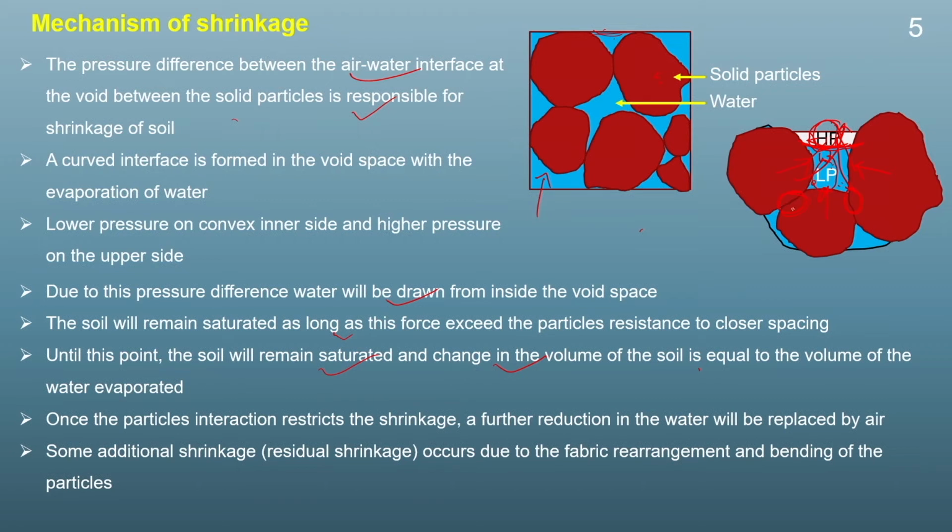But once this resistance force exceeds the pressure difference, then there will be no further movement of the solid particles, and there will be no change in the volume of this soil sample. But with a further decrease in the water content or amount of water, the air will start to enter. So, at that point the unsaturation of the soil takes place, and also beyond this the volume of the soil